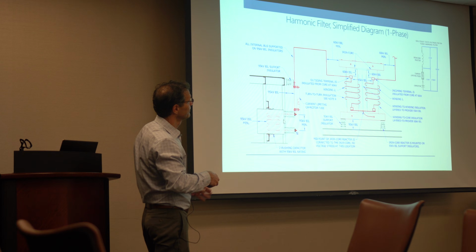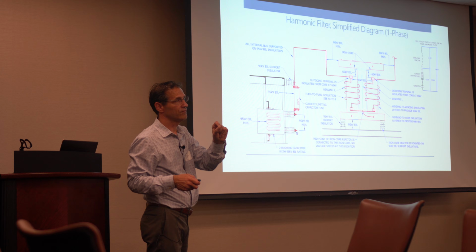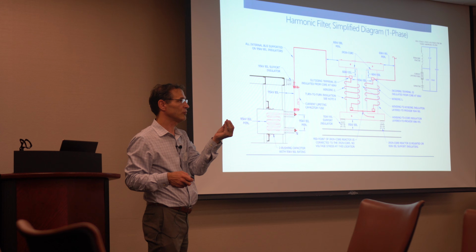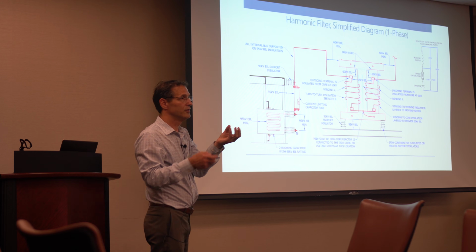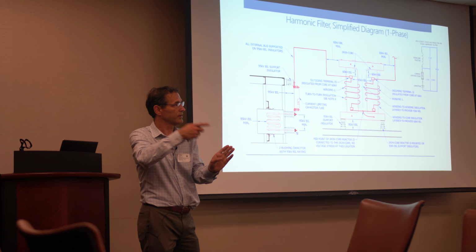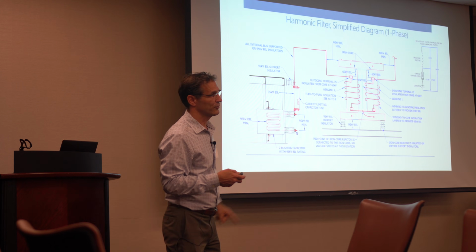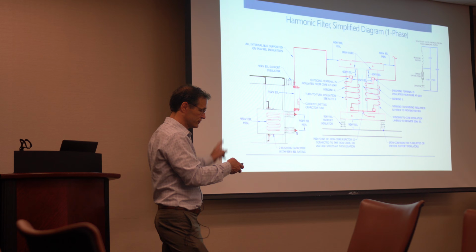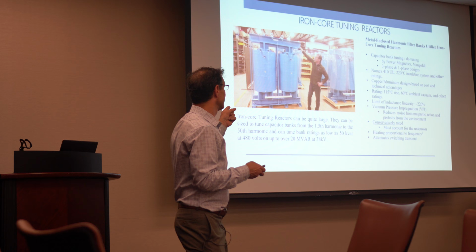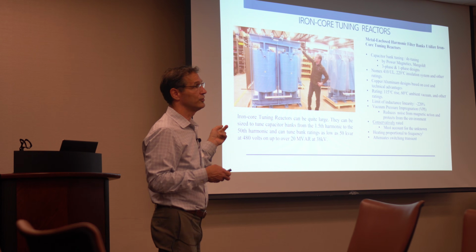So the difference here is we've added a reactor. That reactor is 1/25th. If it's a fifth harmonic filter, it's 1/25th. You've only taken away a little bit of the megavars. It doesn't add or change a lot. The filter bank is acting as a capacitor bank, so it's still putting out reactive power. What was the cost to go up so significantly? It's that reactor. The reactor costs money. And I'm going to show you why. It can be expensive.